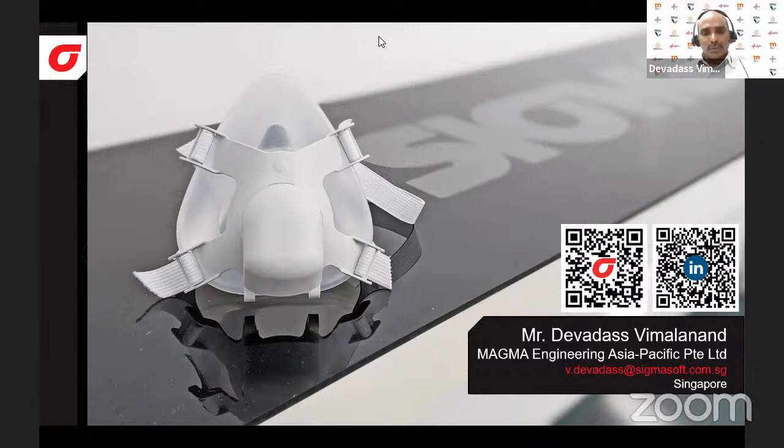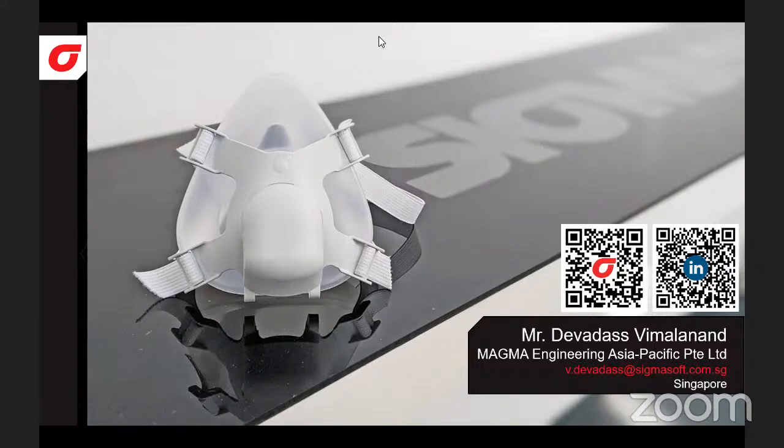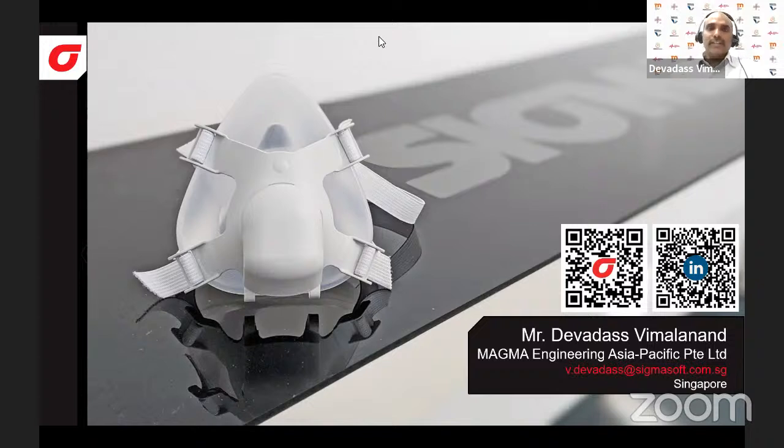If you have a few designs, for example, the first one, the gate location, is a kind of DOE for me. We put in different gate locations, and we ask SigmaSoft to choose the best one, which takes less pressure or has a balanced pressure distribution. Then SigmaSoft will show us the 12 o'clock gate point. So it is possible to find out. There is no limitation for that.